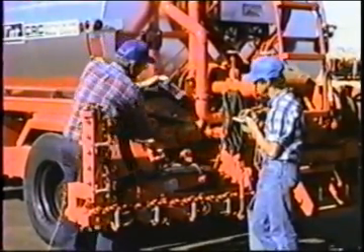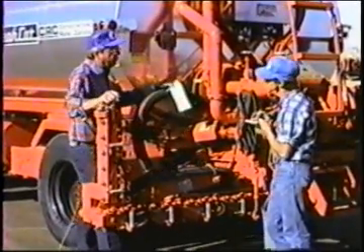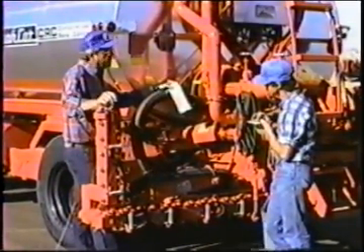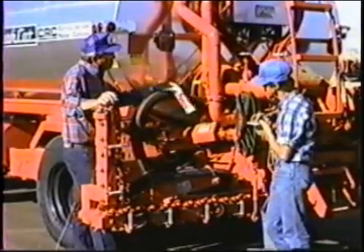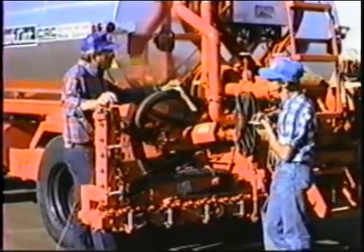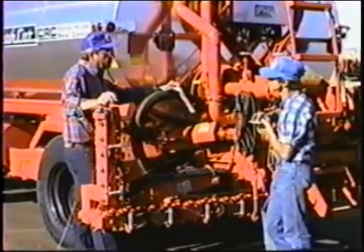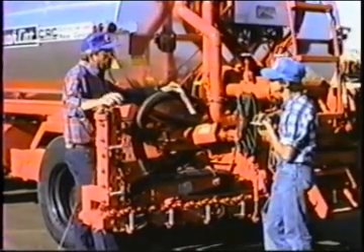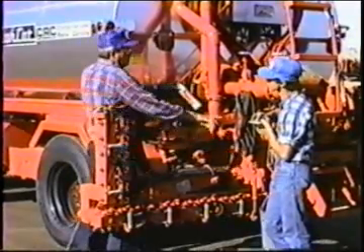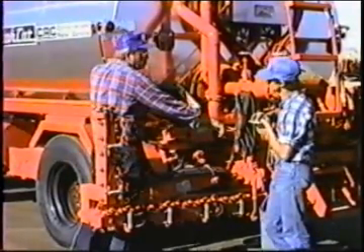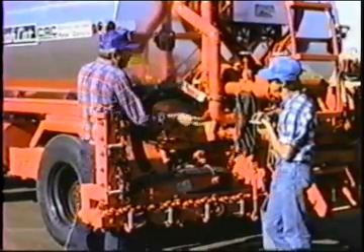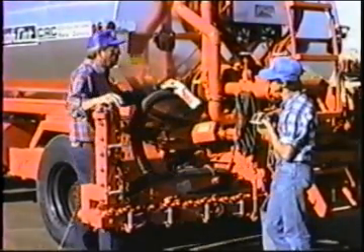Okay, this hydrostatic transmission is driven up from the truck transmission power takeoff or the crankshaft of the engine. Once we have made that setup, that is, we have set the displacement of that hydraulic transmission, we have picked a ratio in that transmission that gives us 135 gallons per minute at 400 feet per minute. Everything here is tied to the truck engine.